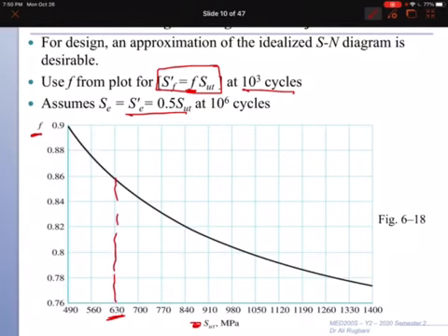Using this curve, you can read F. F in this case is just below 0.86. So we'll make it, this is 0.85, make it 0.858 for you. Okay? And this will give you a value for strength of failure at 1000 cycles.